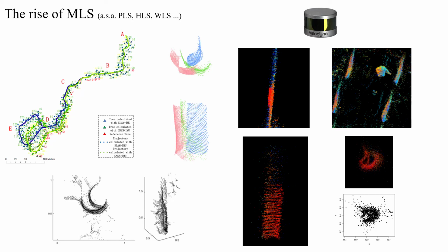And when you think about applying the low-cost portable sensors like the Velodynes, in which you have already by default from the manufacturer a higher error in terms of point precision, about 2-3 centimeters, then those drifting errors become even more apparent, as you can see by those cylinders here that have multiple walls, one inside the other, and it really doesn't make sense.